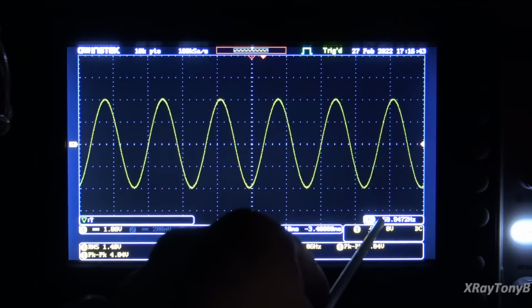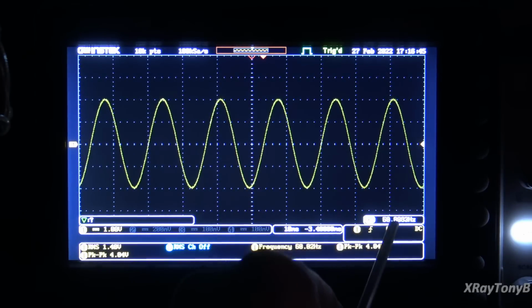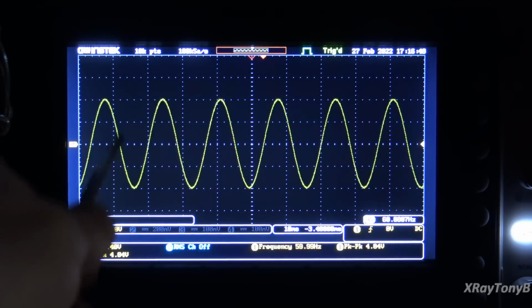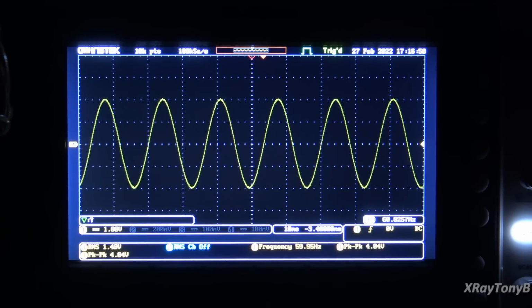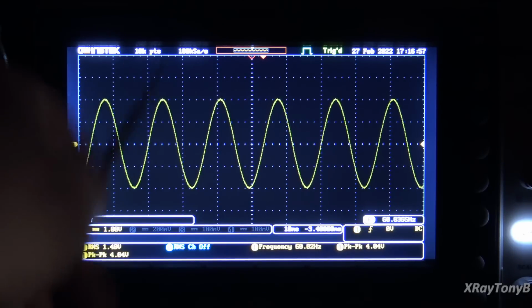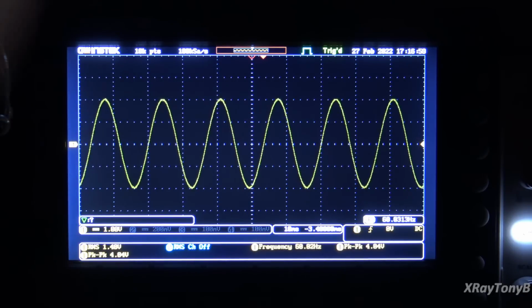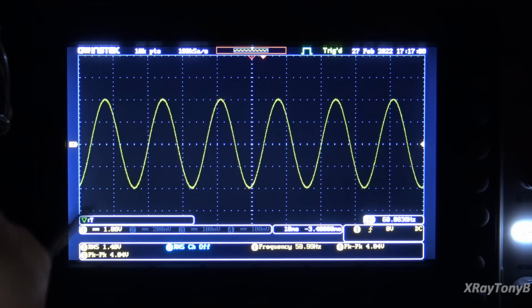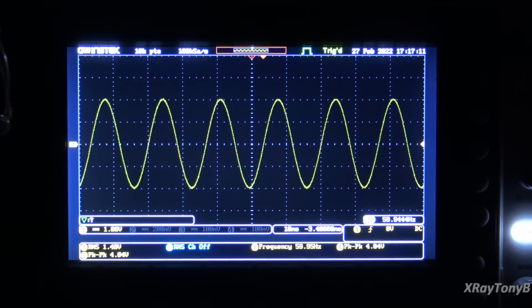And you can see the little frequency counter down here says 60 hertz. So this is your 60 cycle signal, or a representation of what it would look like coming out of your AC mains. Now, of course, your AC mains has a lot more voltage than this. It's 110 volts they call it, but it really isn't exactly. We'll talk about that in a minute. So we now know this is an AC sine wave, and it's 60 hertz, and that's what's in our mains. Now I'm going to show you a different signal.